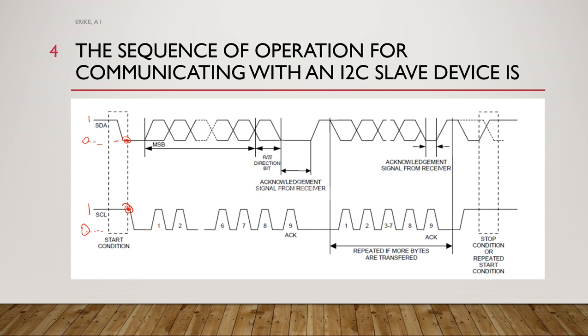Okay, so the slave device that is connected to the bus now compares the address. The slave device is not just one. All the slave devices, when they see the address in the bus, compare the address with the address that was assigned to them. All right.